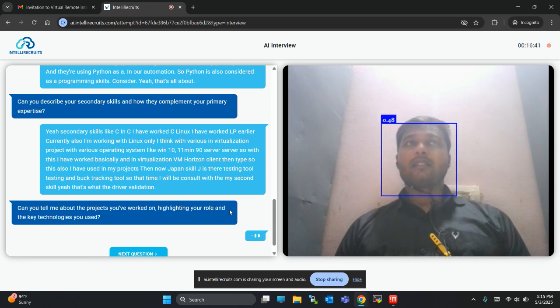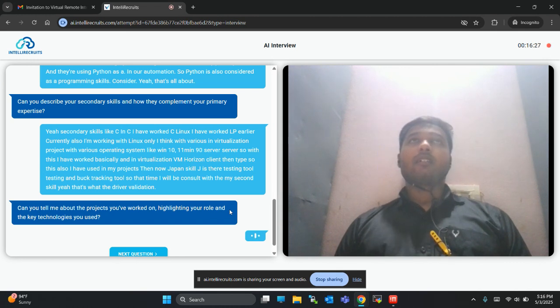Then we need to flash the firmware first, then we need to flash the NVMe which we are using, with the latest version provided by the client. We are flashing that. Then the build we are flashing on that board, and then we are starting our execution basically.